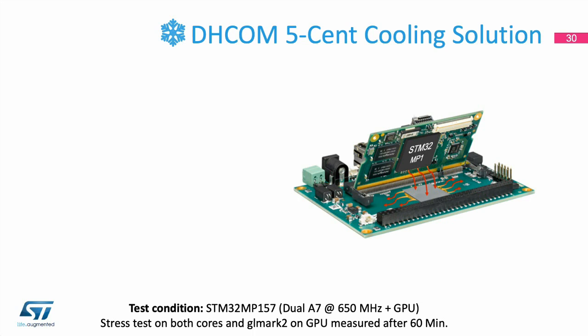The main motivation for this solution was to reduce the CPU temperature without a complex heatsink and to increase the lifetime of the chip. With our so-called 5-band cooling solution, we are mounting the CPU on the bottom side of the module. This gives us the advantage to connect the CPU with a simple gap pad to the mainboard. On the mainboard, we have in this area a copper pad without solder resist. This pad is connected via standard vias to the internal ground plane of the 4-layer PCB.